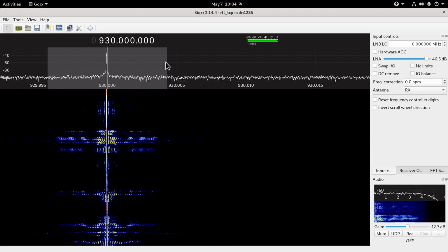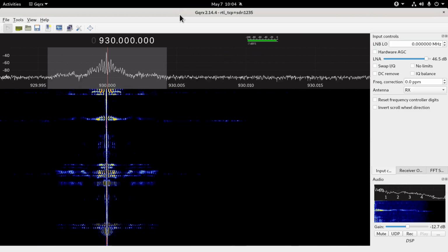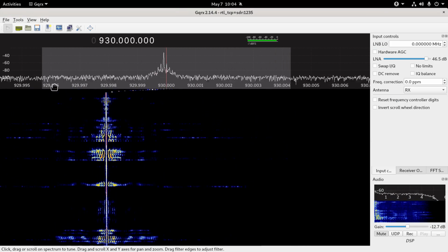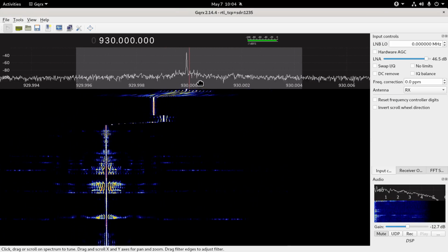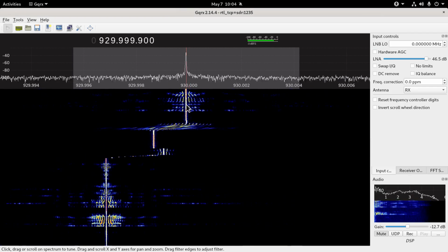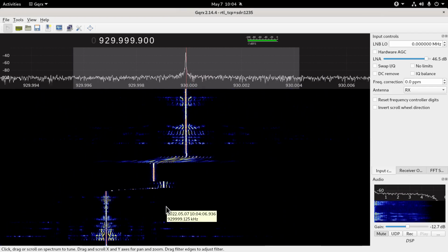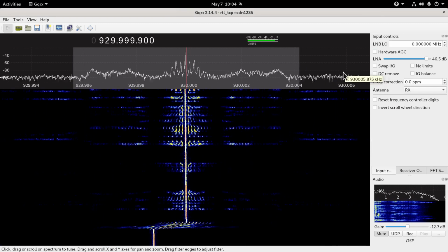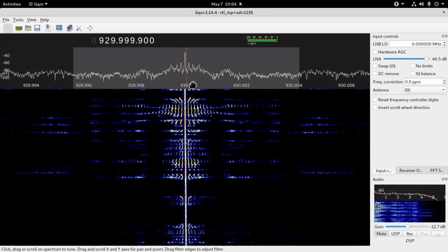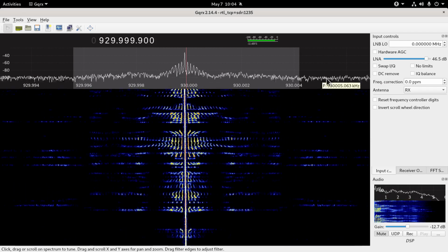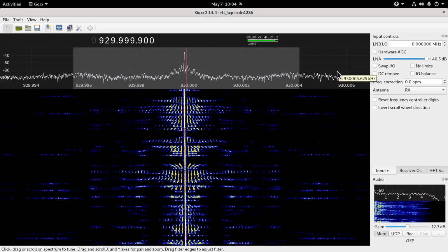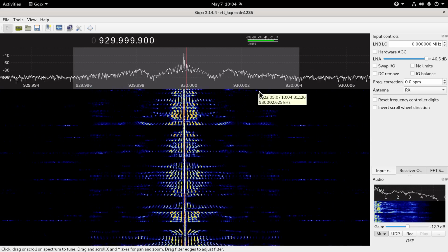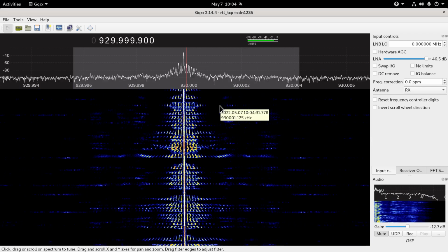So that's all good and well, but let's have a look at this now. Just hang on, let me just mute that to hear myself. If I have a look at this, what's going on here, center it right up. Okay, that's as good as any AM transmitter, except you see how it's still going all the way out to here? That's because I've got no filtering going on, so that'll go as wide as the bandwidth that I'm speaking. So in the real world, you'd put a filter on before you transmit it, so you keep the bandwidth to whatever you're trying to keep it to.